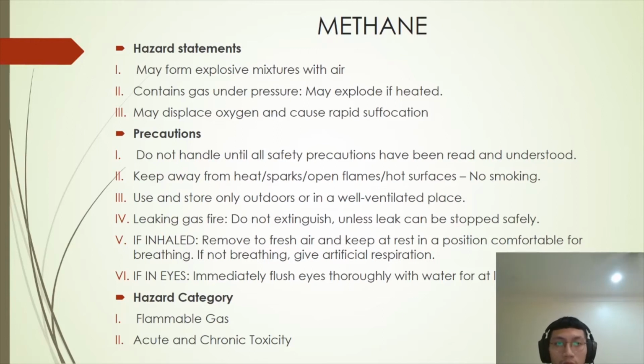Okay, the hazard statement shows that methane may form explosive mixture with air. Besides that, it contains gas under pressure. It may explode if heated and may displace oxygen and cause rapid suffocation. And lastly, it is extremely flammable gas.